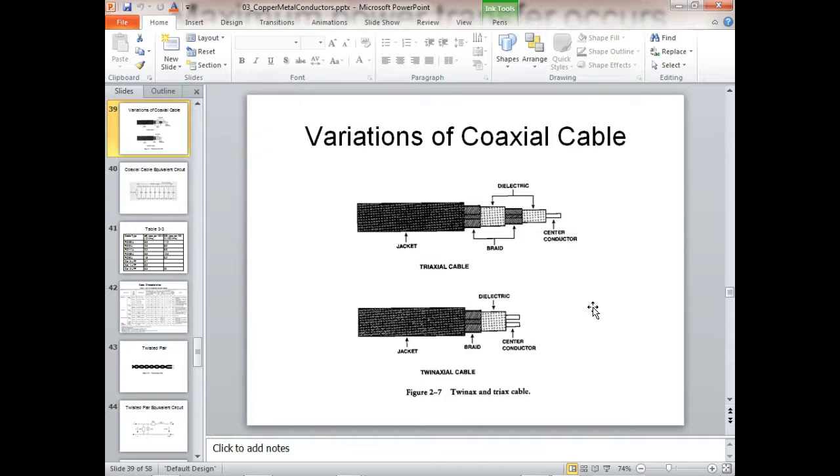It is actually the second conductor, and the spacing between those two conductors is what's so critical to set up that impedance, right? You understand? And the one on the bottom, that's flat cable going to the antenna. Flat cable, they have two wires. This is a duplex shielded cable. The twinplex that they use on a 300 ohm cable doesn't have a shield on it. But the spacing is critical. You see how far those are apart, and that sets up the impedance of the cable, the spacing of that brown dielectric that's actually in there.